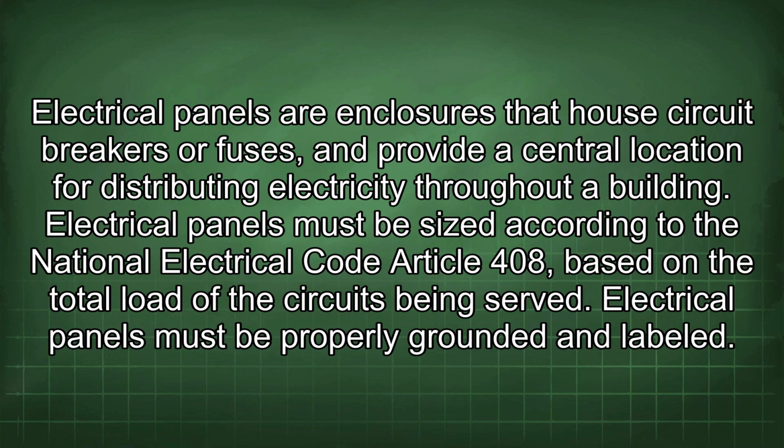Electrical panels are enclosures that house circuit breakers or fuses, and provide a central location for distributing electricity throughout a building. The electrical panels must be sized according to the National Electrical Code Article 408, based on the total load of the circuits being served. Electrical panels must be properly grounded and labeled.